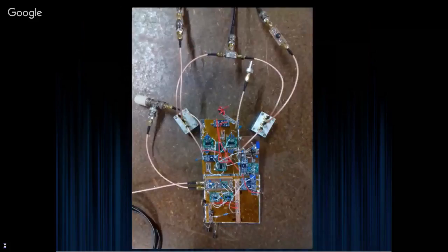Okay, so that gives you a little bit more context as to what's happening here with all these flying leads about the place. The top one in the middle is the 10 megahertz in. So it's the 10 megahertz intermediate frequency coming in. And then the top left and the top right are two low pass filters for ensuring that you remove all the harmonic content from the mixing process and the square waves used to drive the mixers.